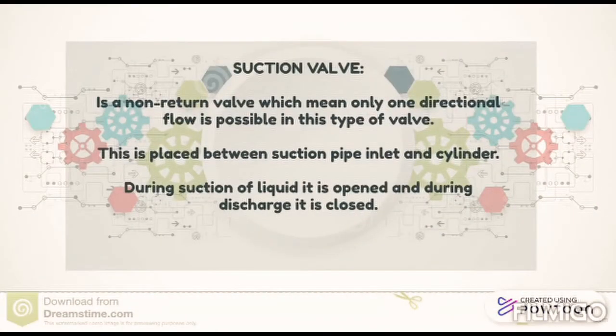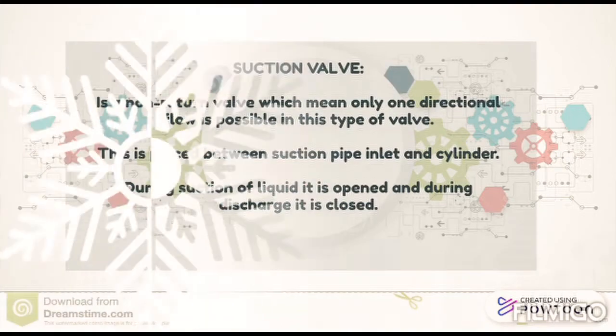Suction valve is a non-return valve, which means only one directional flow is possible in this type of valve. This is the space between the suction pipe inlet and the cylinder. During suction of liquid, it is open, and during discharge, it is closed.